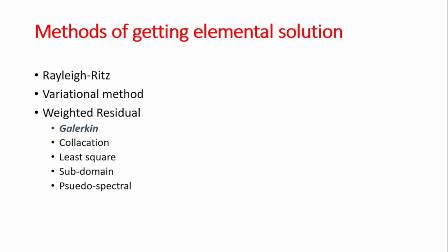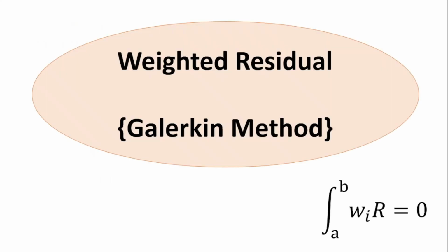So if you are using finite element software, for example, the software would have embedded one of all these techniques in its program, which is used to seek the elemental solution. Then it solves for all the different elements that the domain has been meshed into, and brings them back together in what you call connectivity to form one singular matrix. Then it solves it just the way you would solve simultaneous equations using matrices.